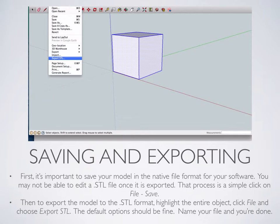The next step is to export it to .stl format. And to do that, you need to select your entire model. To select it, you either triple click or you can highlight the entire model with the arrow tool. And then from there, you go to File, and instead of Save, you want to click on the Export STL option. It'll give you a couple options for saving, like whether you want to use the metric system or inches, and whatever the defaults are generally fine. Make sure you give it a unique name, and from there, you're pretty much done.